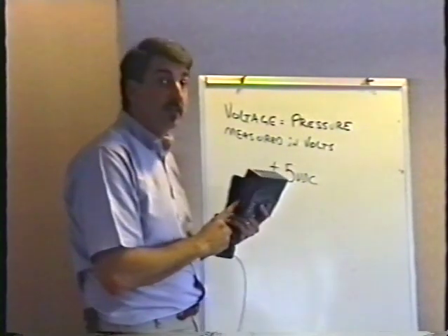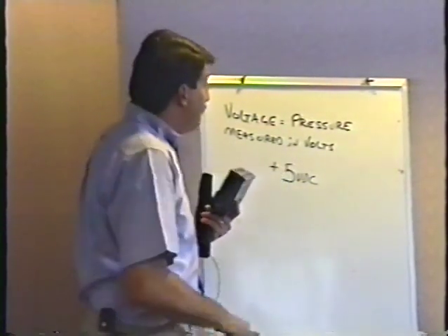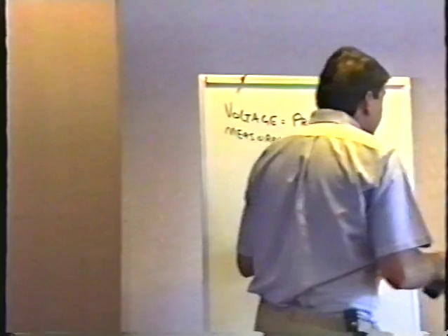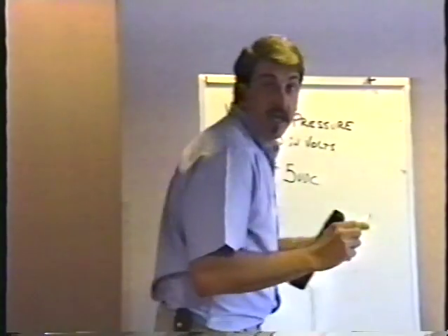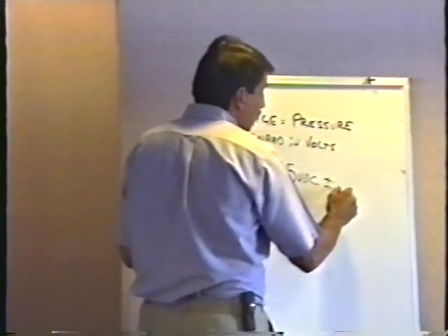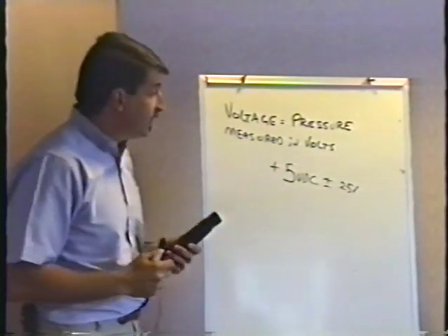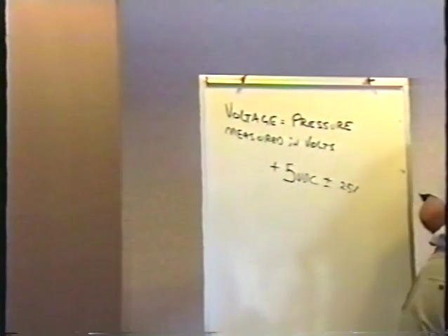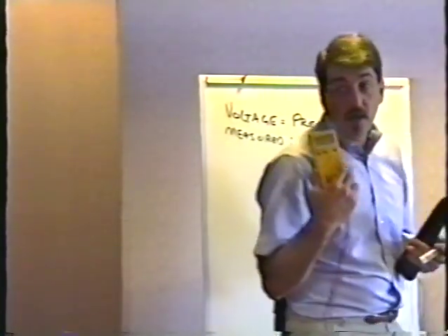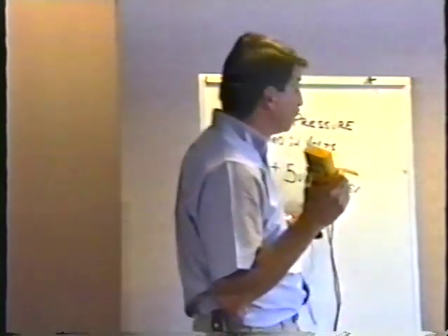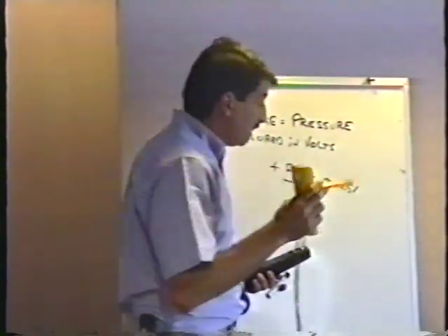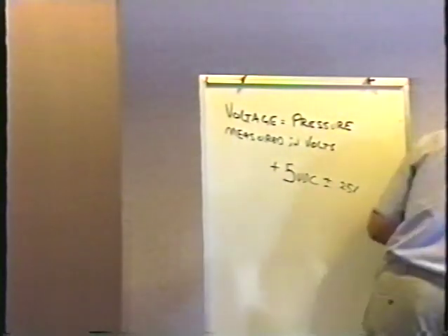We'll talk more about this. We'll talk a lot about this, in fact, because this has to be very exact. The 5 volts DC can only vary plus or minus a quarter of a volt before we start to see problems. That's one of the reasons, in fact almost the main reason, why you want a digital multimeter, so that you can check it accurately, because that 5 volts really has to be accurate. We'll talk a lot about that as we go through the class.